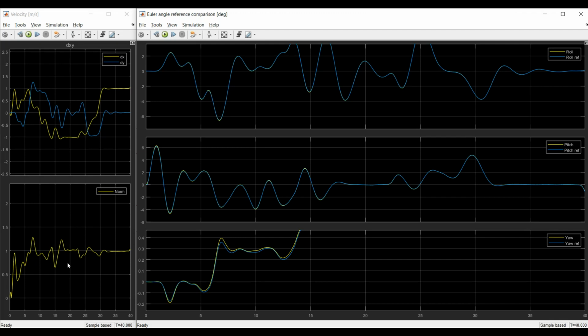The places where it deviates is actually when there is a large curvature, where it's more feasible for the robot to slow down to achieve better tracking, but this is again a tuning question. So in this case, it has been tuned to achieve more accurate tracking of the path over accurate tracking of the velocity.